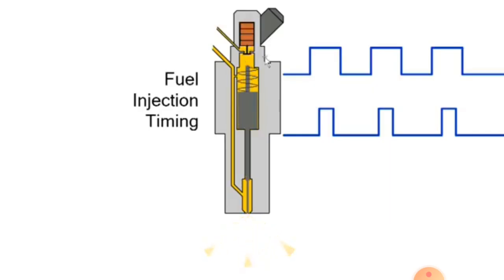Fuel injection. Injects fuel according to inputs from the accelerator, airflow sensor and common rail fuel pressure sensor. Fuel quantity can be varied by altering the length and number of fuel injector pulses. When operating in closed-loop control, fuel injection is determined by the exhaust gas oxygen sensor.